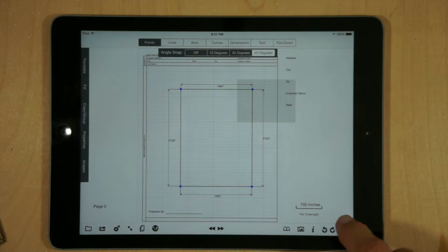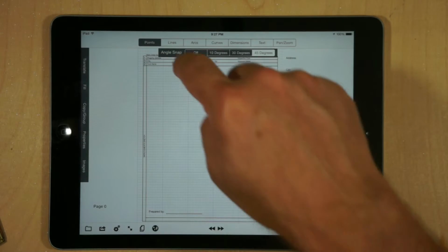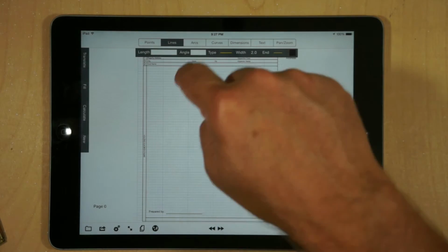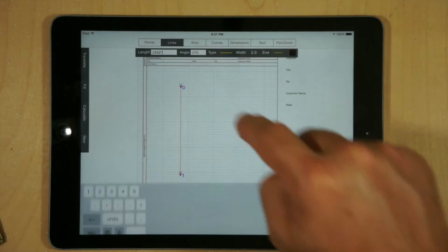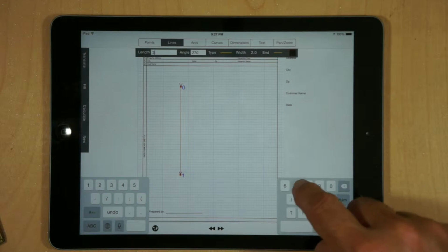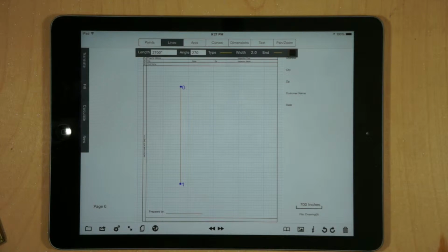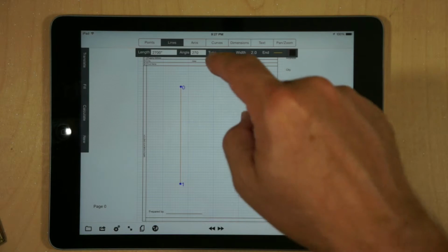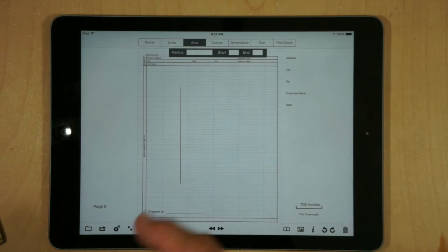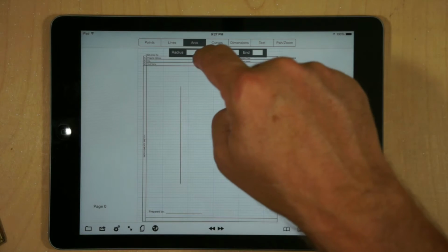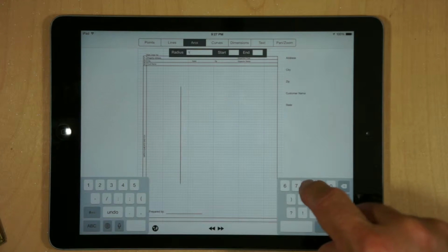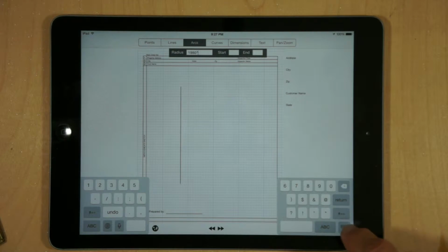Now, a better way of doing this, and we'll go ahead and delete this and start over again, is we'll start from the far wall, and we'll put in our 2,700 inches. Now, rather than actually just go with a single dimension here, what we'll do is we'll actually measure this length from both points, and we'll triangulate using arcs. And so the first dimension, just going along the base, is 1,980 inches, and we'll put that in.